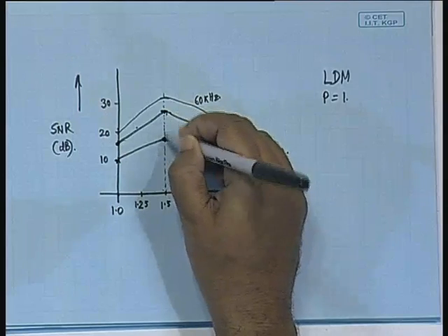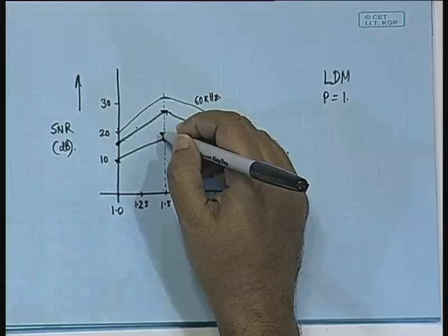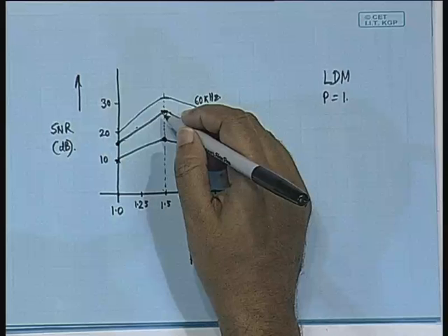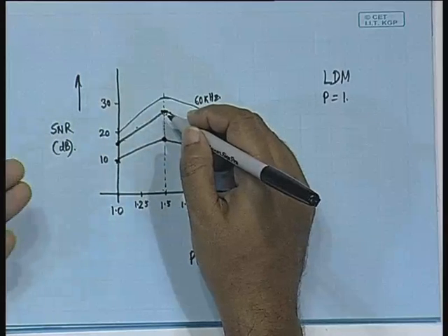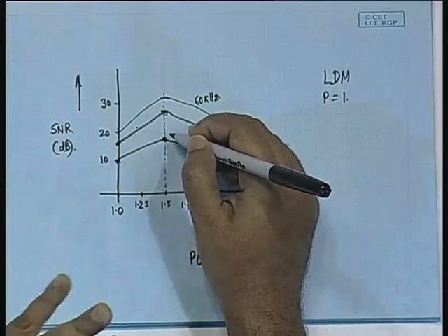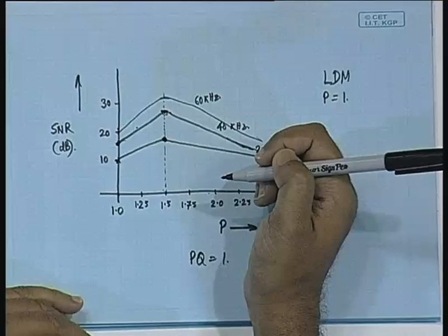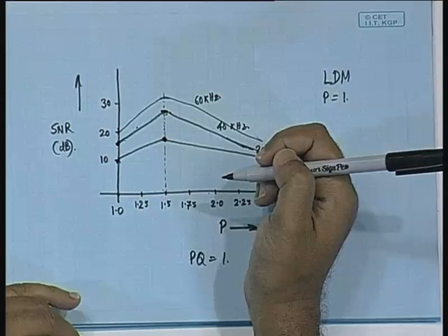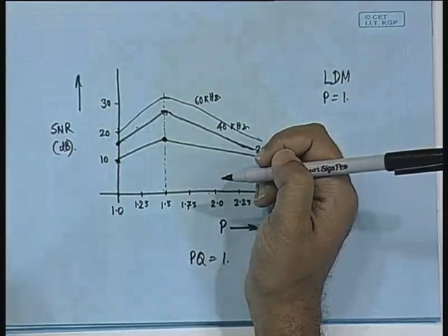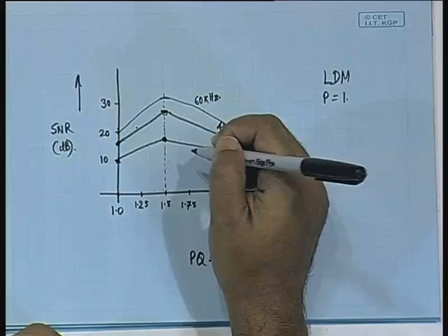If with every bit increase, or with higher sampling rate, we are going to have a 10 dB increase, then definitely one can have better error protection performance, in the sense that to maintain the same SNR we can have a lesser number of bits, and then use that for error protection.